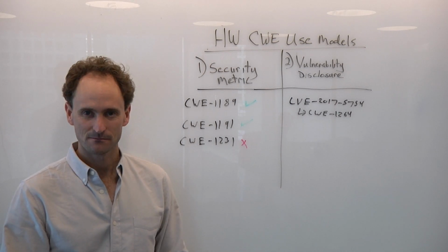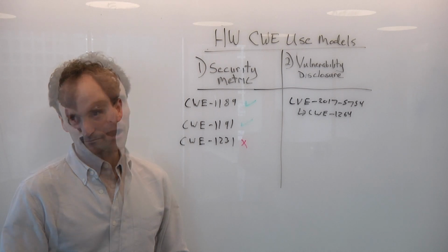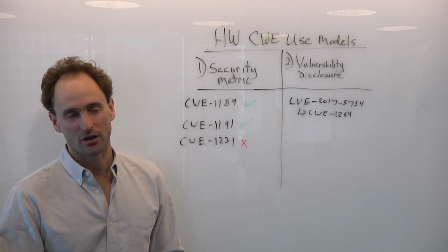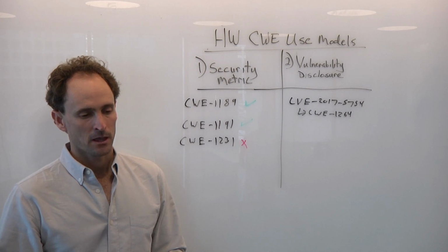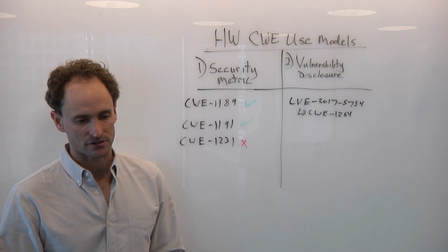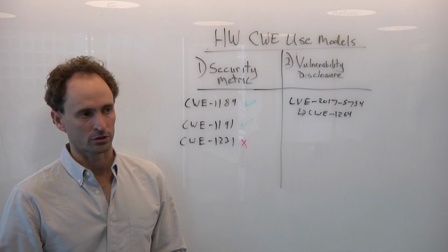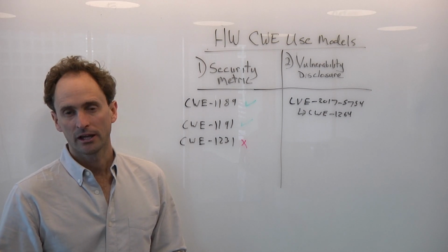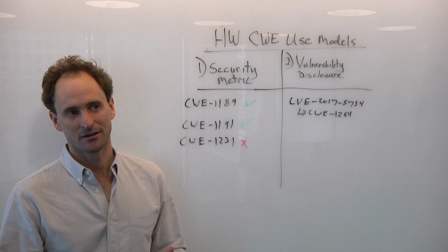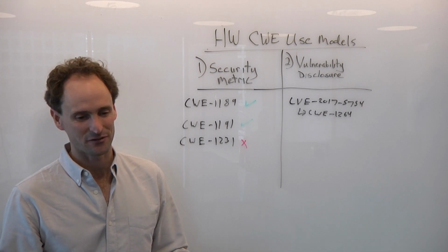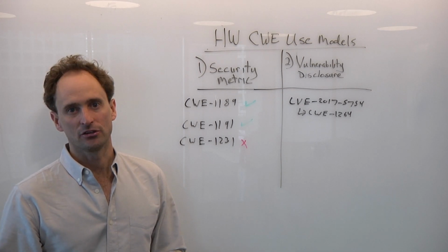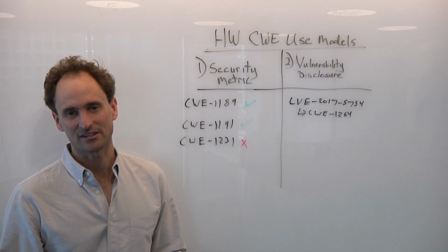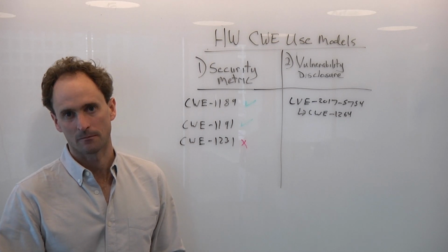So, is there any chip out there that is not vulnerable to anything? From my perspective, no. Every single one, depending on its use model, has a specific exploit. Basically, from an attacker's perspective, if they can cause changes in behavior in the system, extract information, or just cause it to no longer work, and that gives them some gain, then pretty much every chip is vulnerable to those types of things. Even if it's a pure analog chip doing something like an A to D converter, you can actually mess with those types of devices potentially and cause changes in behavior in the system.